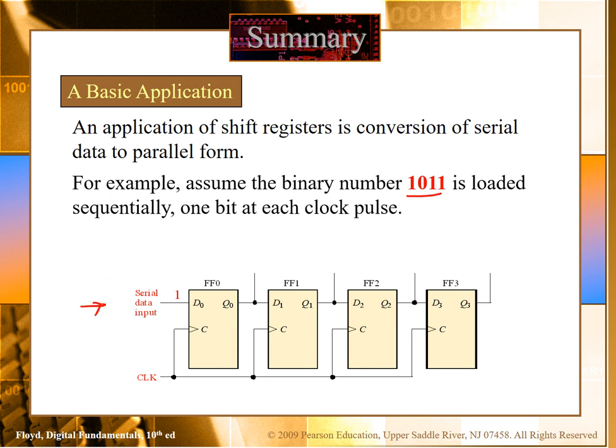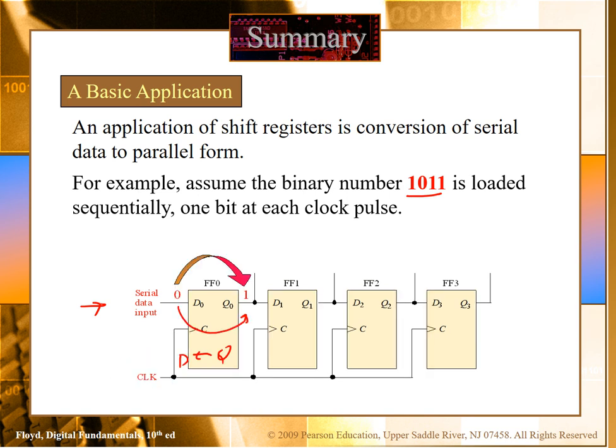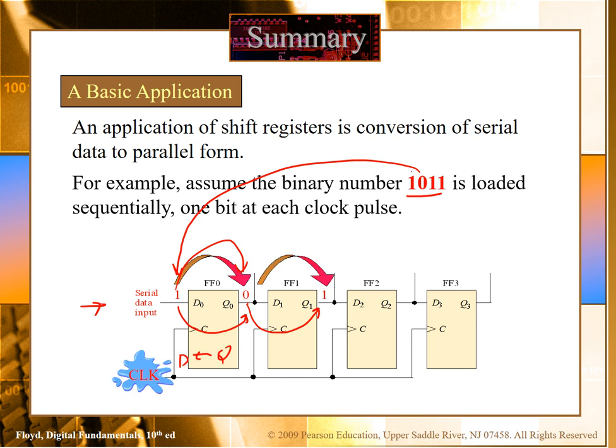Then a clock pulse comes, D flip-flop, Q is following D, so this one comes here. First this one was loaded, then the next 0 is loaded here. Now at the next edge of the clock, this one goes here, and this 0 comes here. So see here.